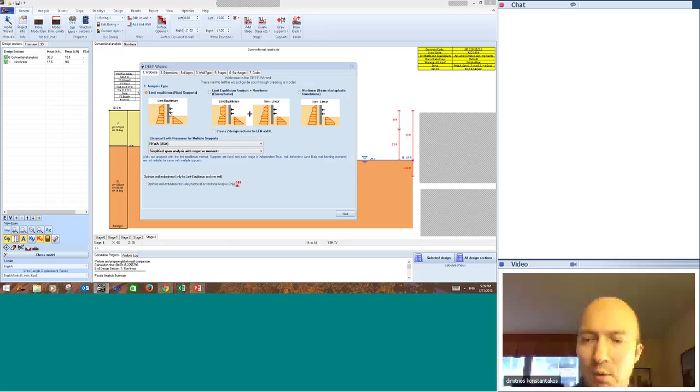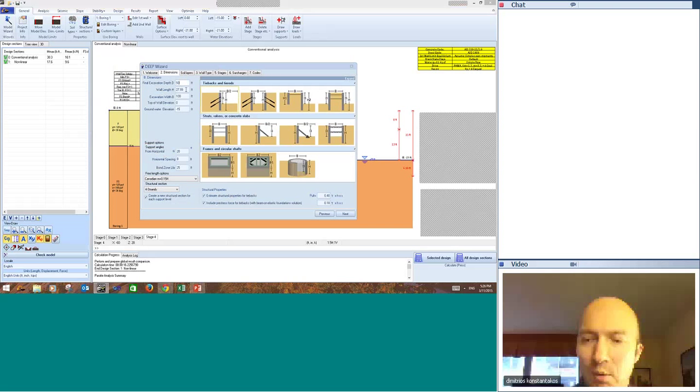So we're going to run, first of all, limit equilibrium analysis. We're going to optimize targeting 1.3 safety factor, per Caltrans. We're going to use the California trenching manual. We're going to make a 50-foot excavation. We're going to start off with a 65-foot wall. Let's actually do a 70-foot wall, that's fine, because we know what the answer is when we get close. So we're going to put the groundwater at elevation minus 35. We're going to do tiebacks. The tiebacks at 15 degrees. We're going to space them at 5 feet horizontally.